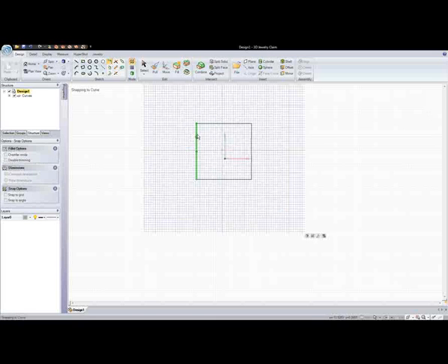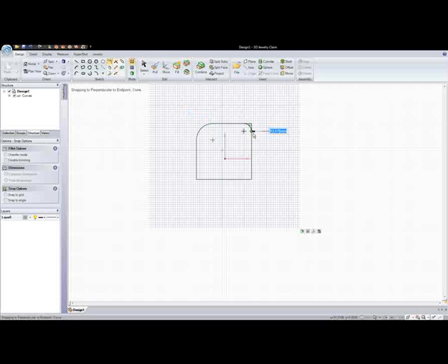I'm going to select the starting point on my curve. Left click to start and then left click to end. So on my second curve I can left click now and I've rounded my corner. Left click again at a starting point, and then you can drag on that other curve and left click at an ending point. To the left we have fillet options.